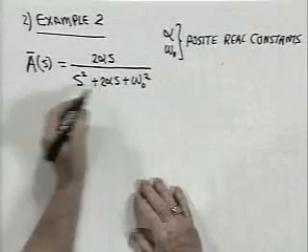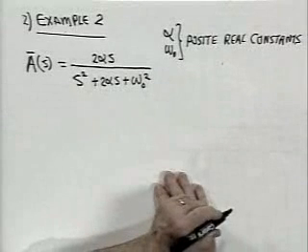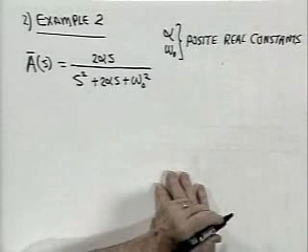When you're working with a function of S, to put it in a form which permits easily the creation of a Bode diagram, you want to be sure that you start with it as a ratio of polynomials. That is, you do not want to have fractions in S in the numerator or denominator. So clear of all the fractions, which will give you something in the form of a ratio of polynomials. In this case, the polynomial in the numerator is a first order, the polynomial in the denominator is second order.